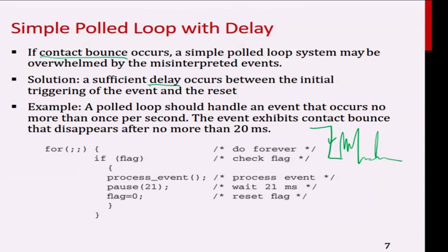So this whole code here may actually execute within this time frame itself before the bounce can settle down. So if I do not cater for that inside my code, I capture the first trigger, go and do the code, then the false trigger also, I go and do the code again. Your code is going to run very fast. So within the time frame of those mechanical transitions, you may already finish what you're supposed to do. Then those remaining transitions will be all false triggers, and your code will still go and execute.